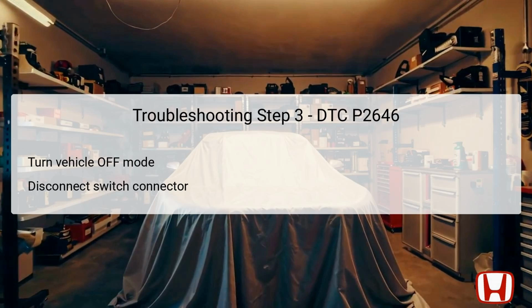Following this disconnection, turn the ignition to on mode again and utilize the HDS to monitor various parameters that relate to the oil pressure switch. You should be looking for the VTEC Press SW status, among other readings, to determine if the current conditions match the outlined thresholds. If the parameters are within specification, it indicates that the wiring and components prior to this point are functioning adequately, helping guide the next troubleshooting steps accordingly.